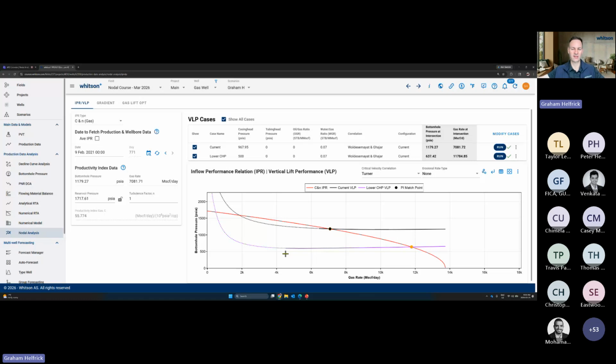It's under less pressure, so it's expanded. And the bottom hole pressure being lower, the gas is also more expanded downhole as well. So when the gas is expanded more under less pressure, it moves faster. And that faster gas, that velocity, that's our friend when it comes to liquid loading. So that's why we can produce to a lower rate before we worry about liquid loading at a lower wellhead pressure.